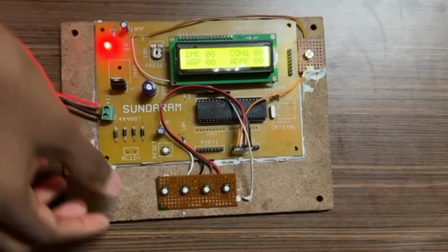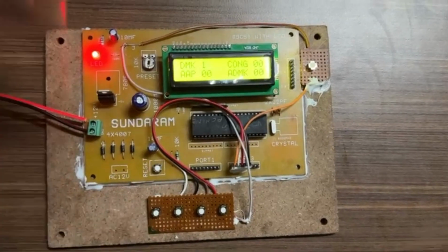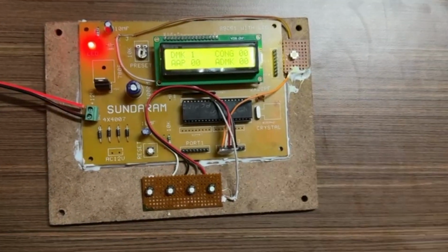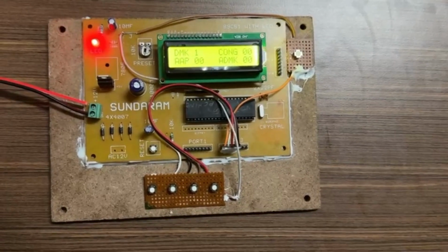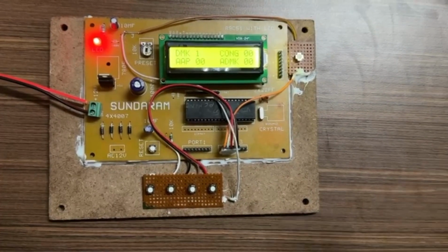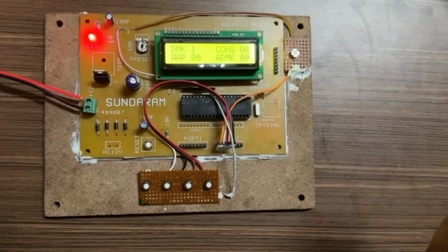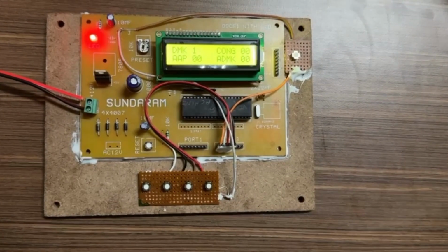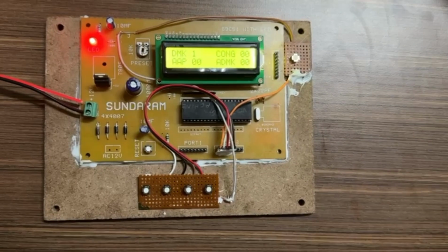Each time a voter presses a party button, the party's vote count increments by 1 and it's shown in the LCD. The 8051 reads button inputs via port 3 and sends the result to the LCD via port 0. The system uses digital logic, delay generation and LCD interfacing techniques. It is a simple, reliable microcontroller-based voting system.